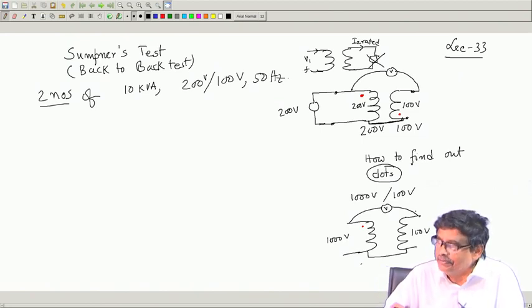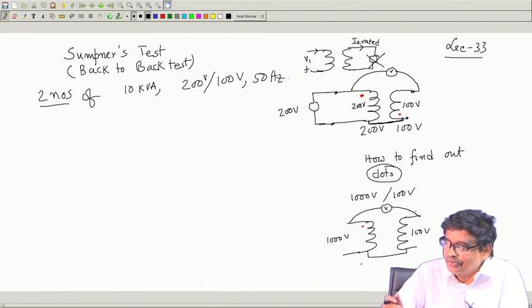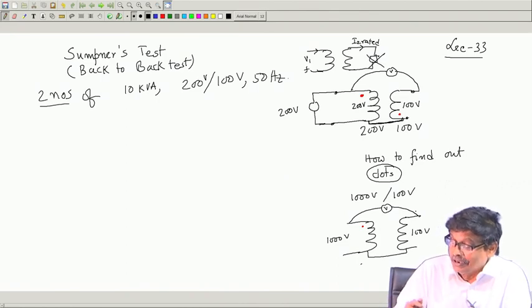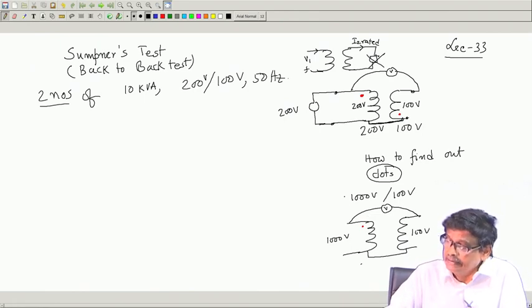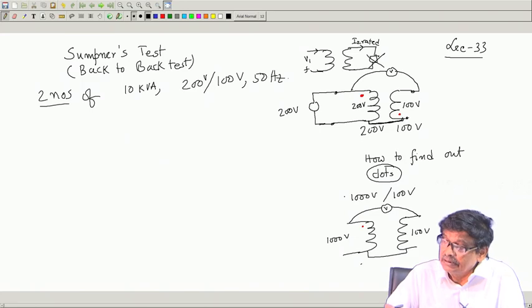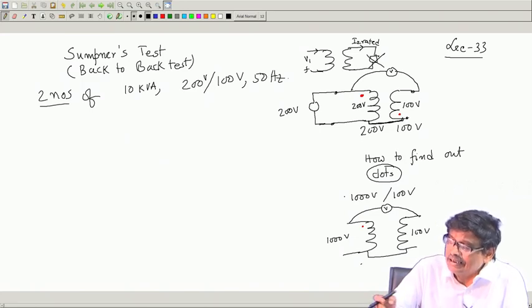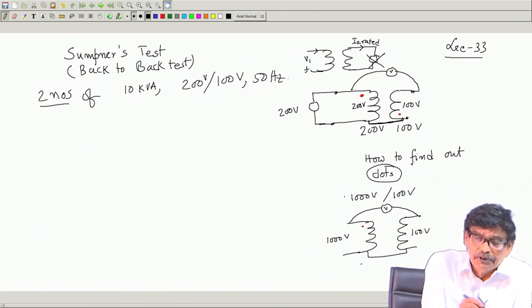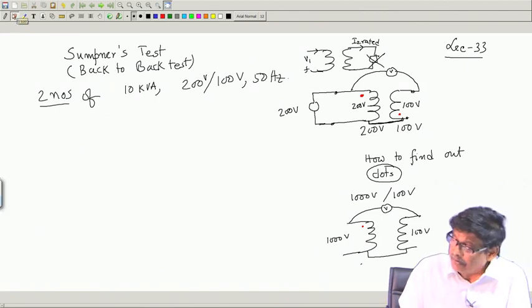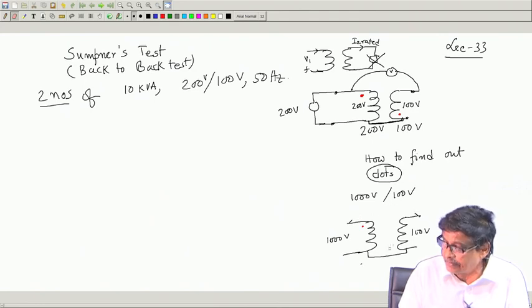Therefore, it will be very difficult to distinguish these two readings confidently. Okay. So, in such cases, when the voltage ratios are high, it looks like this method is not reliable. So, what people do in this case, for very large voltage ratios, is another simple test, and that is called the DC kick test.